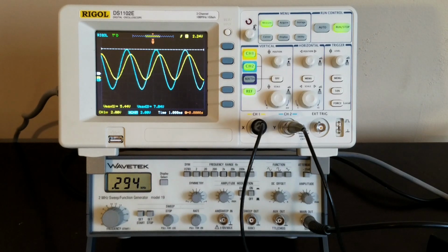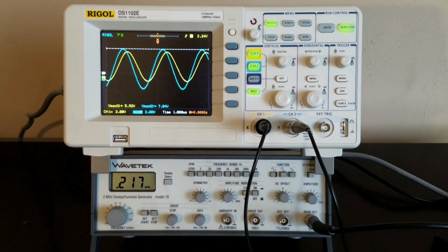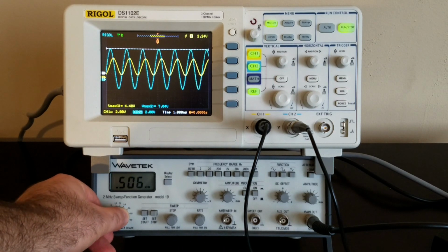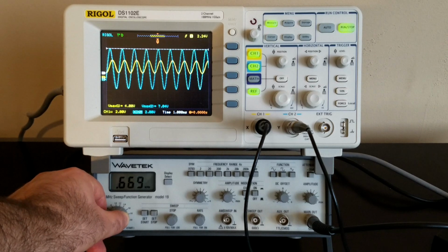So the main take-home message is, if a sinusoidal input signal is injected into an RC circuit at a given frequency, the output signal will have the same frequency with a certain magnitude and a certain phase angle relative to the input. So let us verify this experimentally. Remember that the yellow signal is the output signal. We adjust the frequency of the input signal, and as we increase the input frequency, what can we observe?